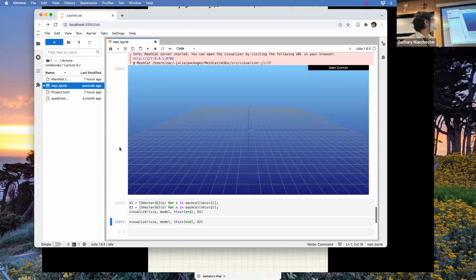So that's LQR, we don't care about that. But here's the one with the updated stuff. Now I'm only allowing it to tilt a few degrees, and it's doing this nice, slow, gentle thing. I'm not going through the floor. I'm staying within a nice region where my linearization is still good, all that kind of nice stuff. And this is quite a nice trick to play.